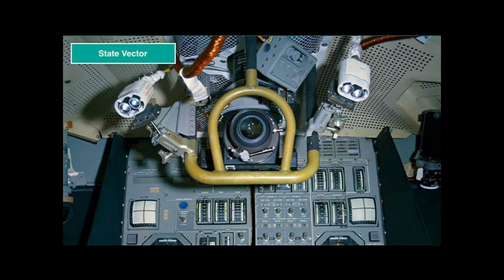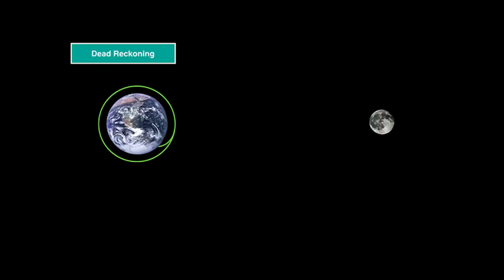In the lunar module, on the other hand, the whole optics hardware was trimmed down for weight reduction. Any alignment requires rotation of the lunar module. This is mostly used to determine the landing site and support the rendezvous maneuver. It even lacks the software to perform positioning in translunar space.